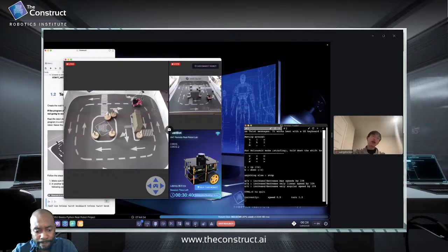So I should have added the algorithm where if it detects something for more than a few seconds, then it should recognize it as a wall. If it recognizes something for more than, let's say, 5 seconds, it's definitely going to be a wall because there's no other obstacle that is longer than the wall.